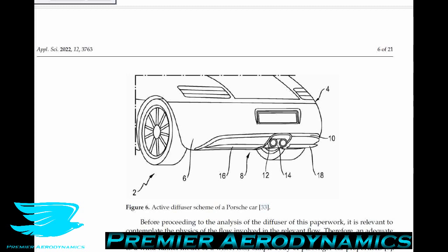But coming back to a car's underbody and how changing the cross-sectional area, and hence the pressure, affects the car. Well, if we reduce the car's distance to the ground, this reduces the pressure of the air in the underbody section, and that increases the downforce because the pressure on the car's roof is greater than on the underbody. So this results in a pressure difference, which results in a net force down on the car. That is the general theory. So let's look at how this idea applies to a car more closely.